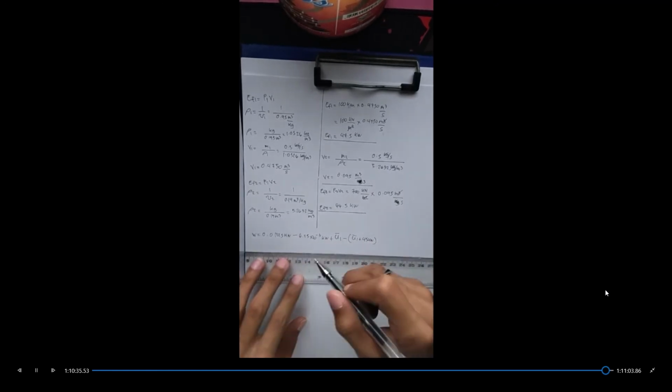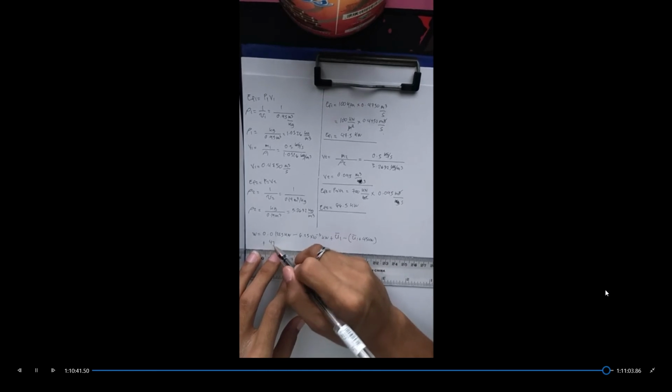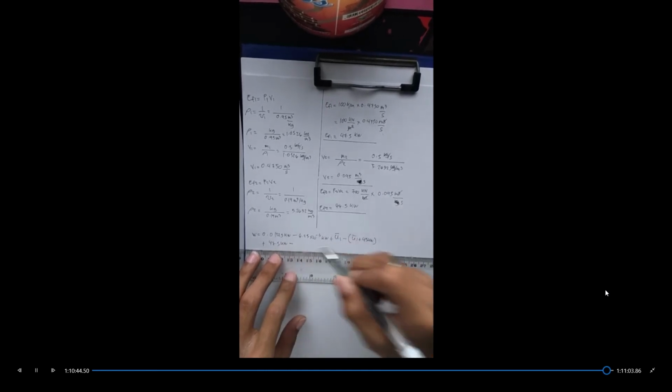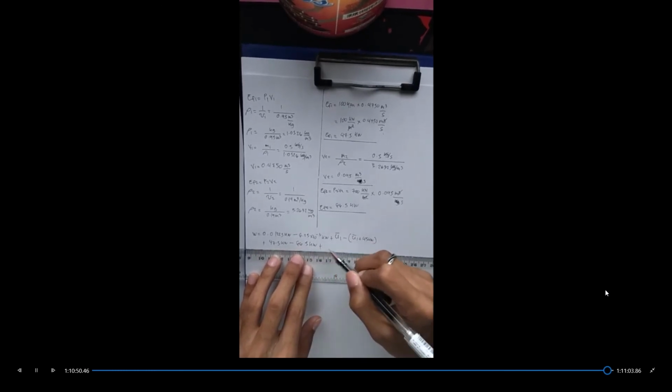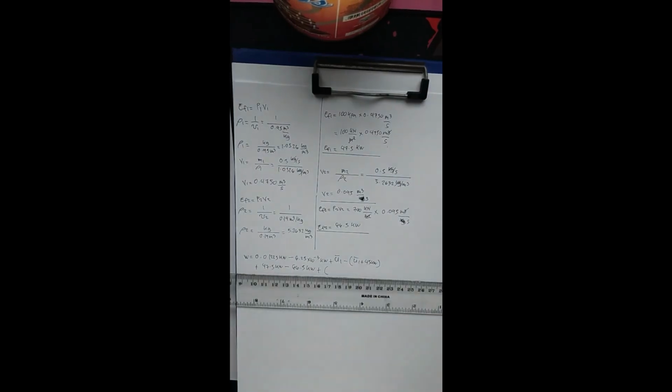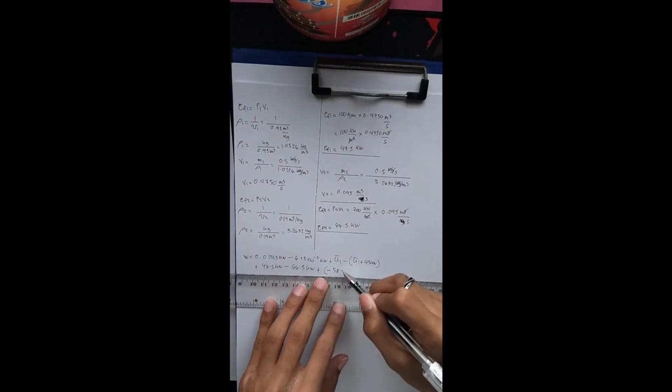And then next is my EF1, which is 47.5 kilowatts, and then minus my EF2, which is 66.5 kilowatts, and then plus my heat, which is negative, because the heat is being rejected through the cooling water compressor jackets, so this will become negative 58 kilowatts.